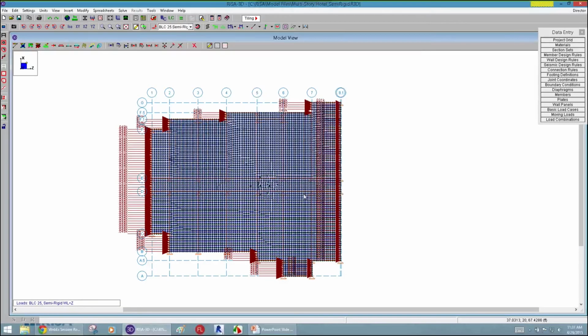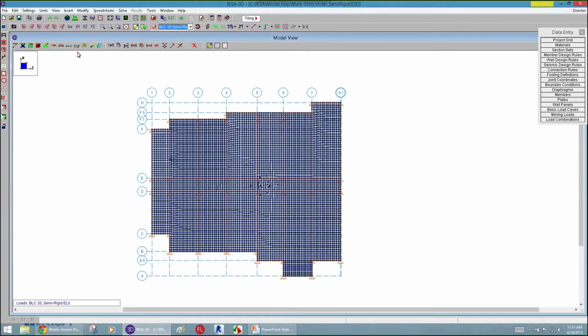The fastest and quickest way to do this, and it's just easy, the way we do it automated is going to be slightly different, a little bit more accurate, but the very quick and easy way is just to take that entire 6.5 kips roughly and dump it into the entire model based on a surface load. I can do that quickly by jumping up to there so we're looking at this view, and I can do that using my surface loads.